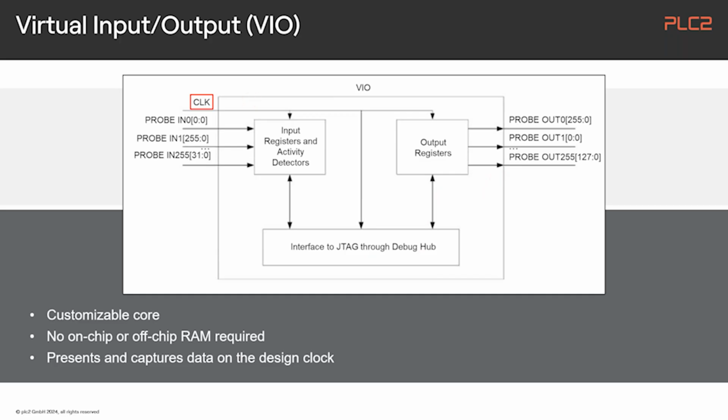This IP block also has a clock synchronous architecture. So this means if we are asynchronous on our host side, those signals will fulfill timing conditions of synchronicity to the connected clock. Perhaps you have 2 different clocks in our design or even more, then you can use multiple VIO cores to bring each probe signal into the required synchronicity as it needs.